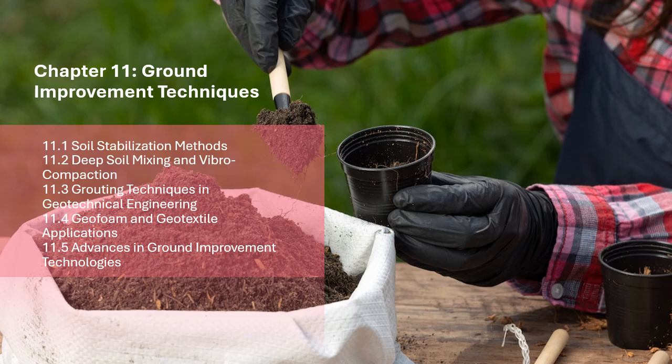Geofoam's lightweight and compressive strength make it an ideal material for reducing the load on weak soils, while geotextiles serve a wide range of functions, including reinforcement, filtration, and drainage. Together, these materials can improve soil stability, reduce environmental impacts, and provide cost-effective solutions for a